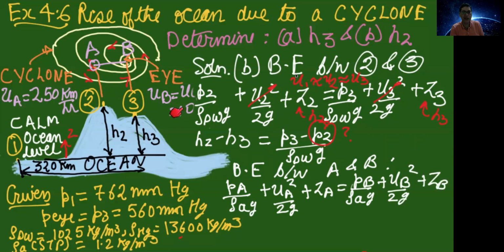So earlier, the density that was presented in the Bernoulli's equation was corresponding to seawater. Now for air, you have a rho A. Now this rho A we will be considering corresponding to the point 3, which is subatmospheric pressure. We are given the density of air at 1. Now here you have low pressure and air is compressible, so the density is varying. So we will apply ideal gas equation and obtain the density at point 3, and that density is presented here.